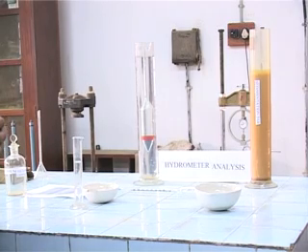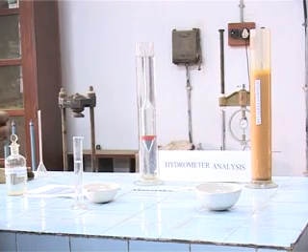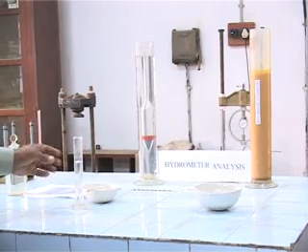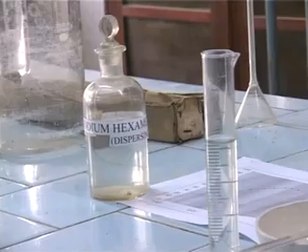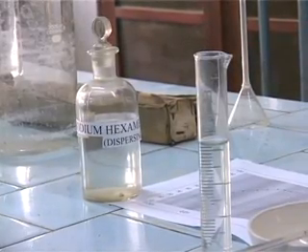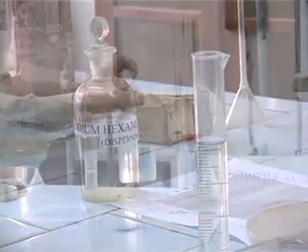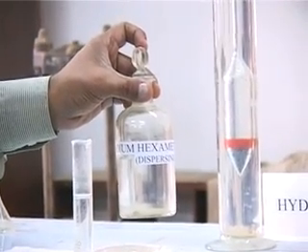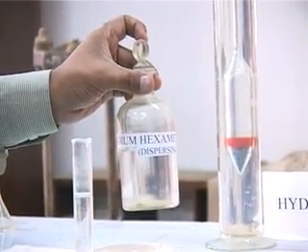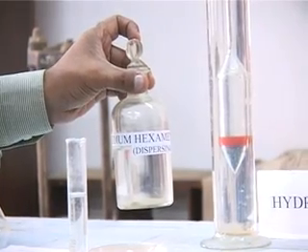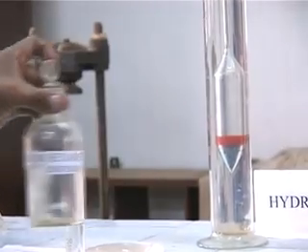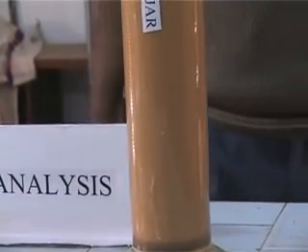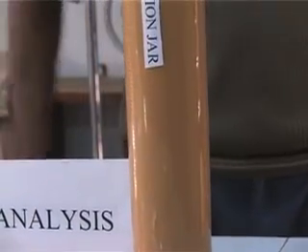a sedimentation jar, and we also mix it up with about 20 ml of sodium hexametaphosphate solution, which acts as a dispersing agent so that individual soil particles do not cling together forming clasts, so that the settlement rate is not wrongly measured, because the clasts are going to settle at a faster rate than the individual fine grained soil particles.